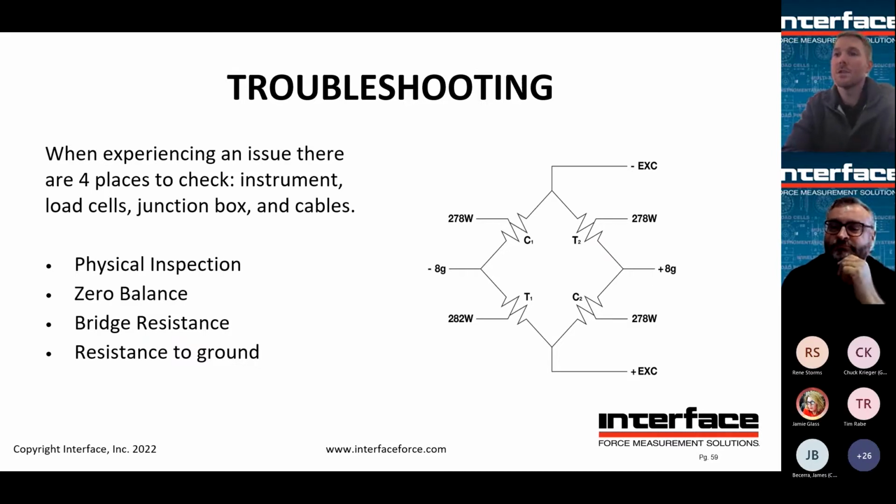When looking at the load cell specifically, look at the gauged area. Are there holes in the potting? Check the cable entrance. Is it bent, cracked, distorted? Look at the cable itself. Cuts, nicks, crimps, abrasions. Water loves to be wicked up through the cable.